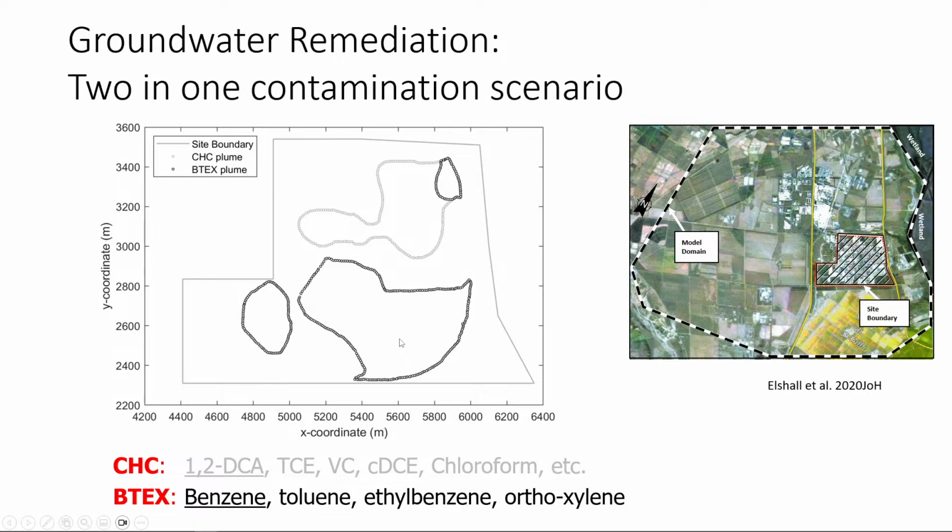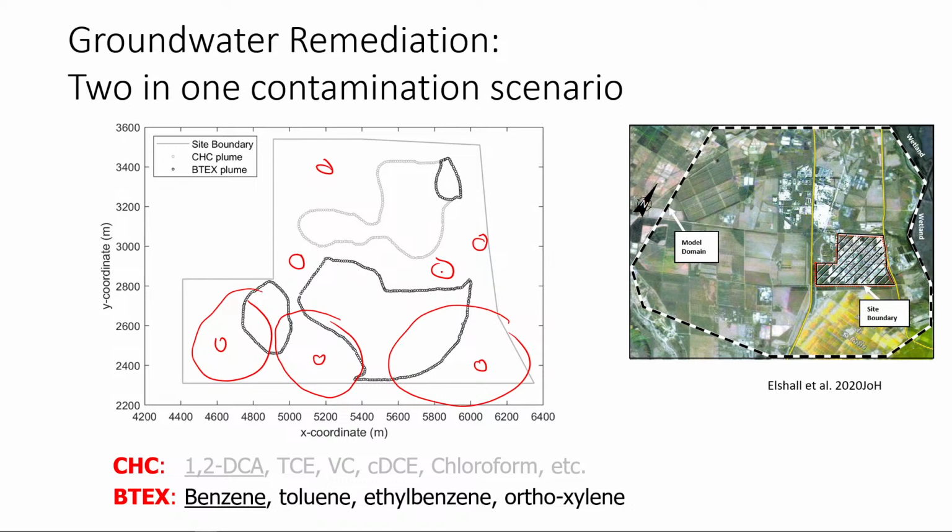Basically, we can put pumping wells here. Let's say a pumping well here, here, here, and here. This one might capture these particles, this one might capture those, and this one might capture those. Oh, you see, this one will capture some of these and some of those, so cross contamination. So the location of this one is not good. Maybe we need to move it a little bit here. And this one might also cause some cross contamination, so you move it here.